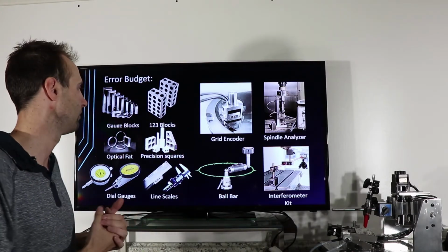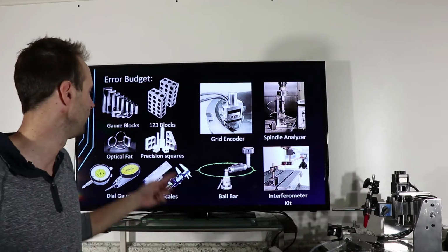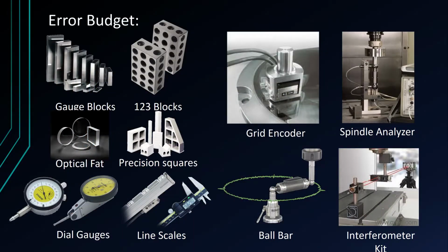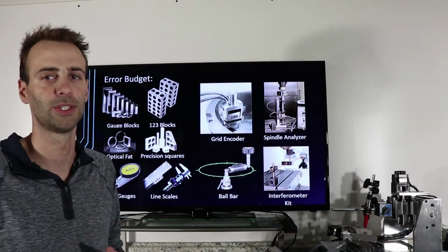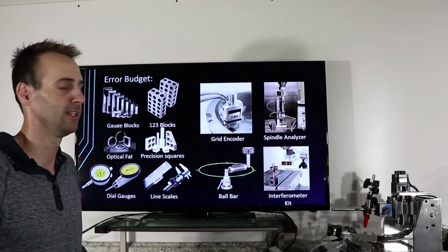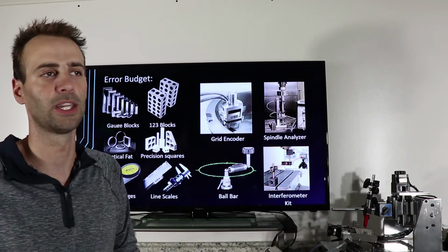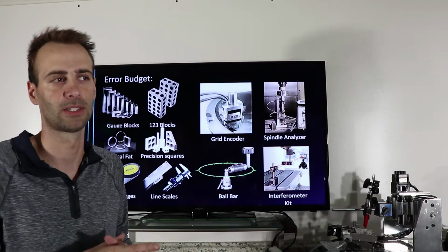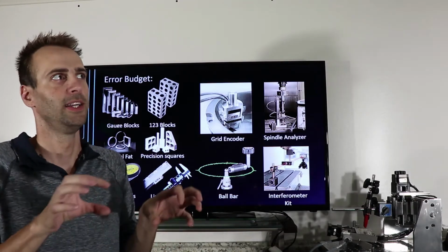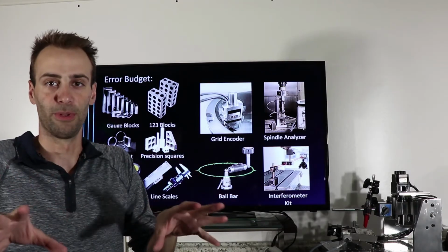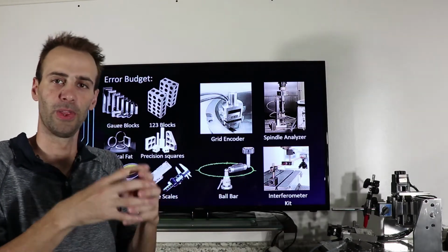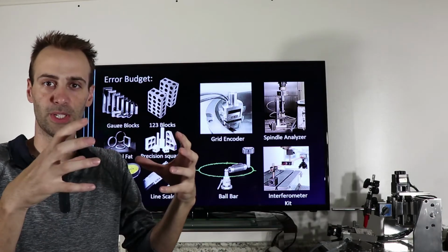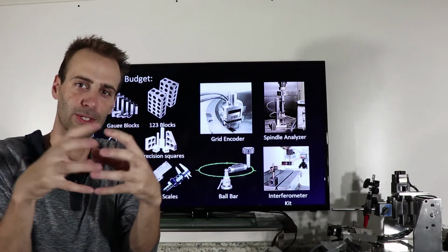But if you really want to spend money on specialized stuff, they do make precision squares where you can get perpendicularity, and you can get them made in ceramic with really high surface finish. You can make them in exotic materials, like Zerodur, for example. It's a material that, to simplify it here, we'll say every other atom has a coefficient of expansion that grows with temperature, and the one right next to it shrinks with temperature.